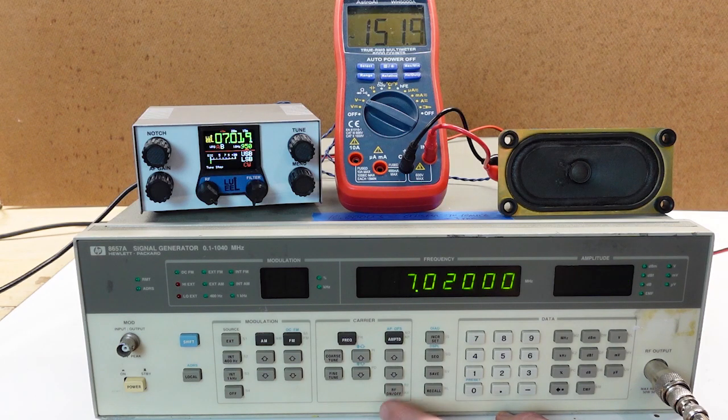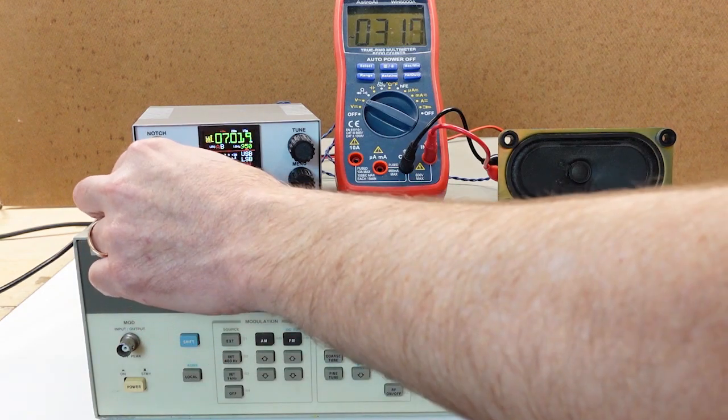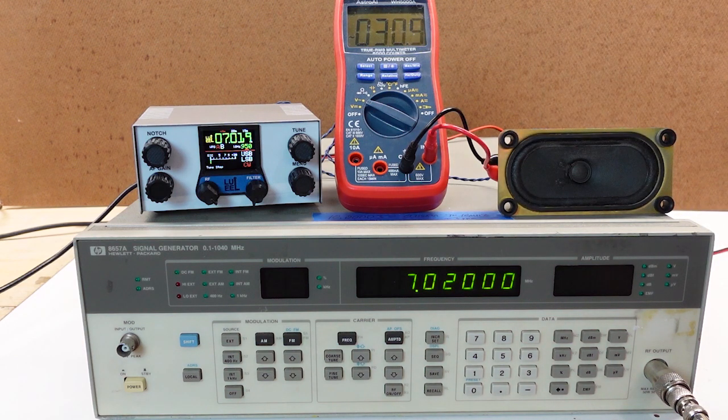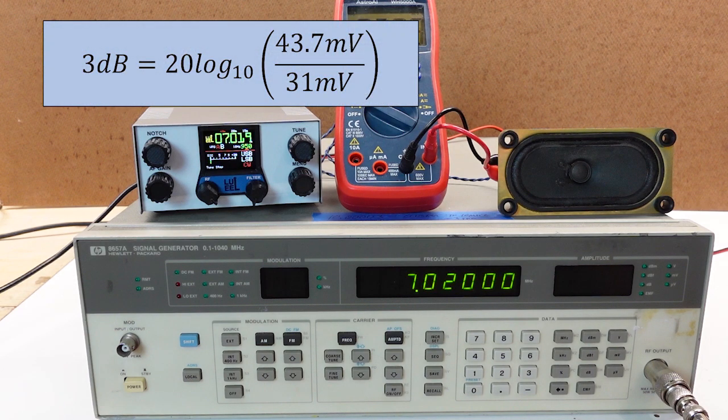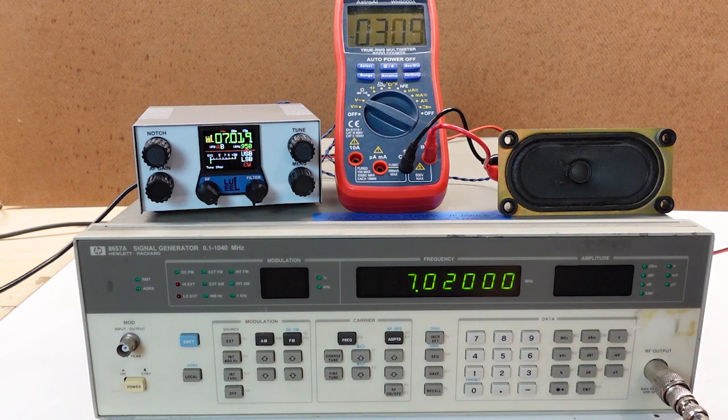That'll work. Okay, the next thing I want to do is set the AF gain to max, again where there's no signal coming out of the signal generator, and then record that value. So that's about 31 millivolts. And because I'm looking for a 3 dB gain above that value, doing the math, that works out to 43.7 millivolts. So the last thing I do here is turn on the signal generator and dial in the amplitude until I hit about 43.7 millivolts.